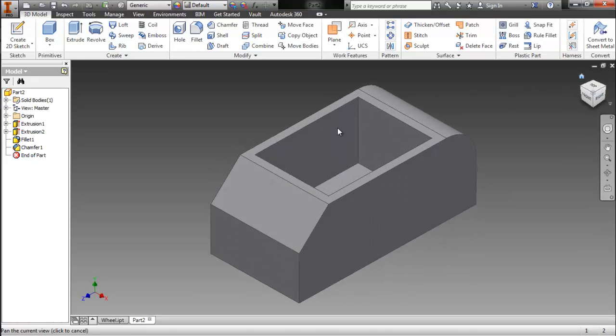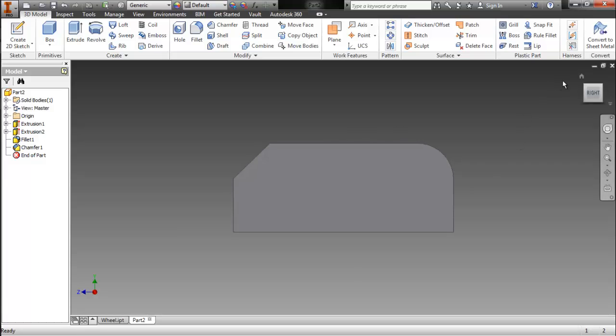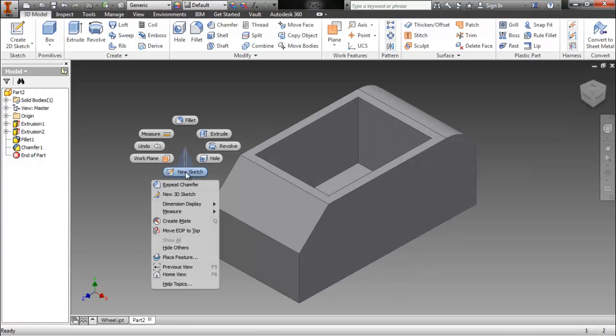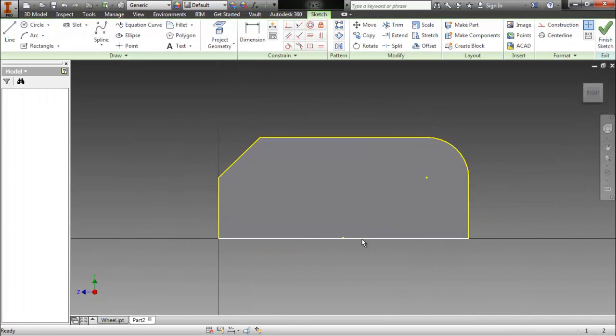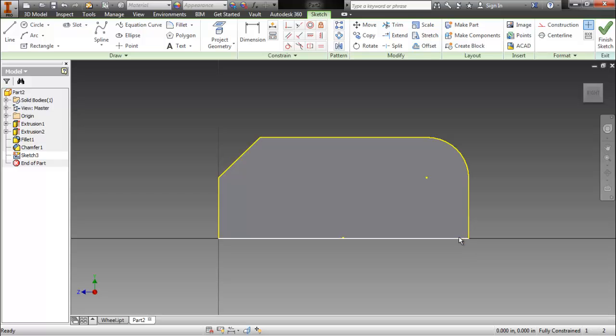And a tool we've used multiple times already, extrude, this hole right here. In order for the wheels to go onto the actual cart, you need holes. That requires taking away 3D material, which starts with a sketch. So I'm going to create a new sketch, click on my surface, and start away. I'm going to make a hole from the center mark 1 inch from the corner inside, up and left, or in the Y and X axis.